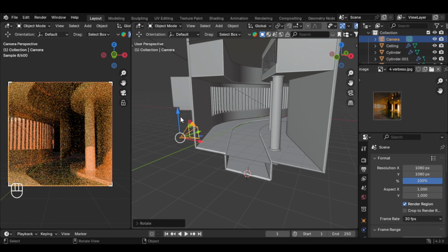Let's first move the building and this little one here, and press Tab and X-ray mode, and press 1 or 3, and let's just select this one here, go out of X-ray mode, and let's just bring them a bit down, so G and Z, to about maybe like this is enough.